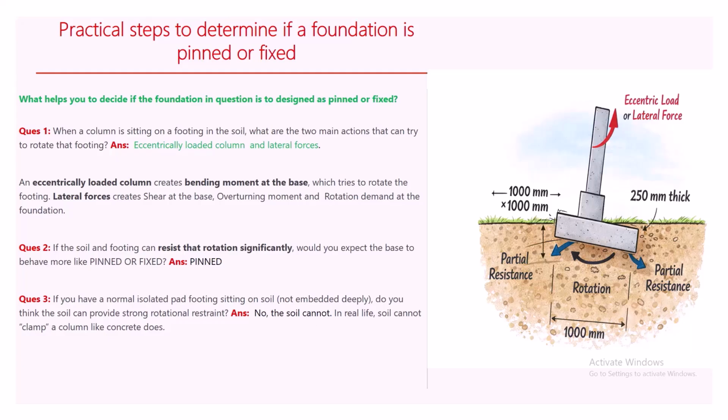In real life, soil cannot clamp a column like concrete does. Soil cannot hold a column the way you know how strong concrete is. So the soil does not behave that way. So these are the questions you ask yourself to actually determine if it's pinned or fixed.